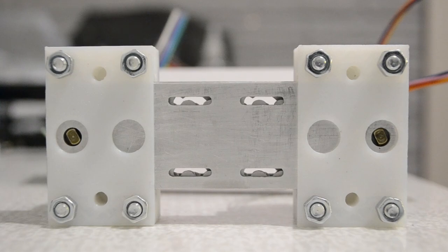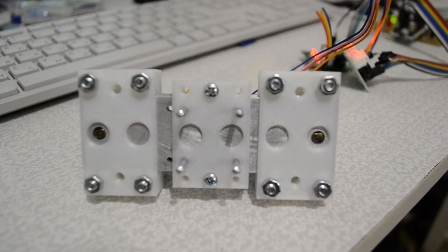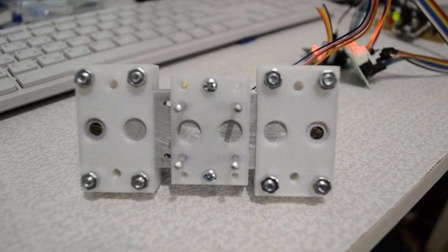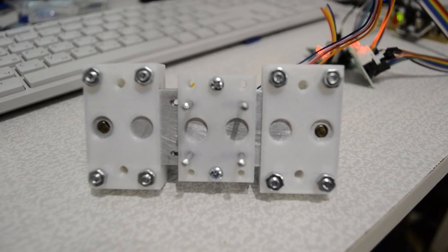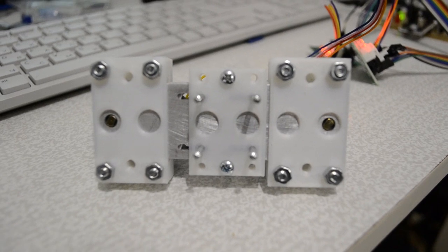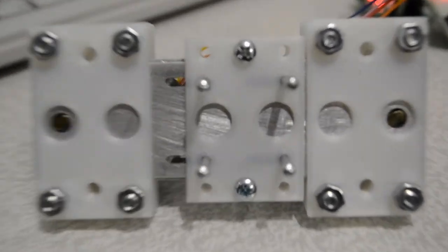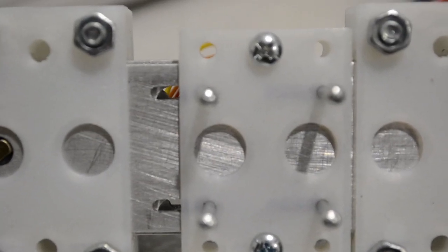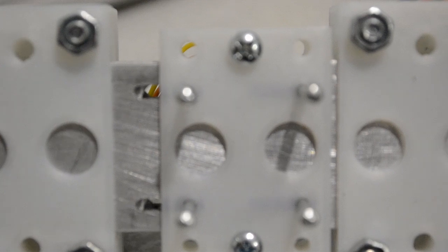Now let's add the carriage. It has pins which are ideally an integral part of the carriage. All cutouts have a width equal to the pin's diameter and they engage with the edge of the cutouts. Cutouts in the plates define the exact position of the pin at every moment of time. Pins and the carriage, respectively, are pushed along the axis due to the motor's rotation.